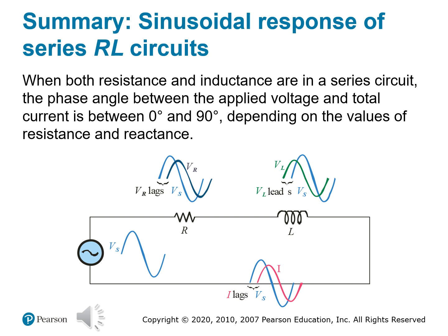So what does that mean for your circuit? If R is large and X sub L is small, the circuit behaves more like a resistor, a small phase angle. If R is small and X sub L is large, the inductor dominates, so you have a larger phase angle. In all cases, current lags behind the source voltage, but how much depends on the circuit design. And this behavior will affect the power factor, which we'll learn about later, timing accuracy, and signal shaping.